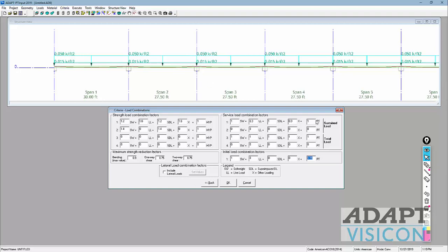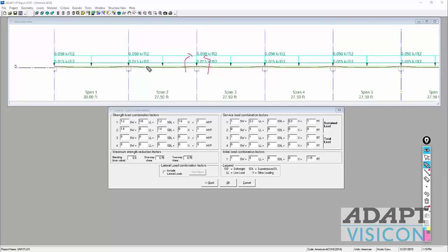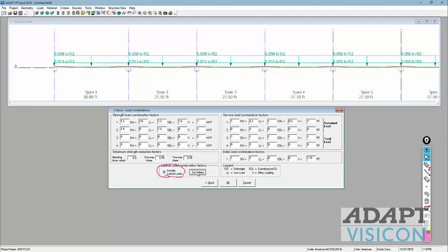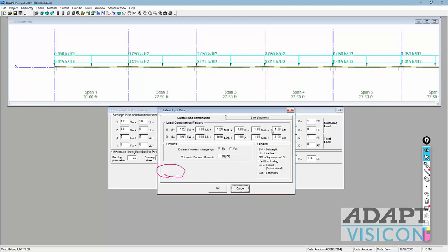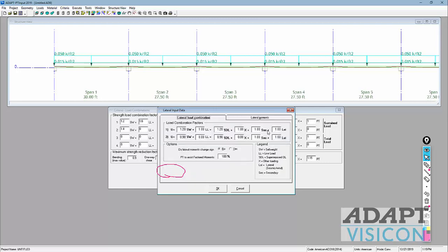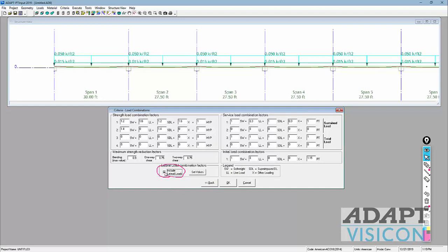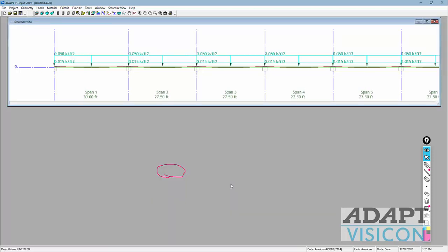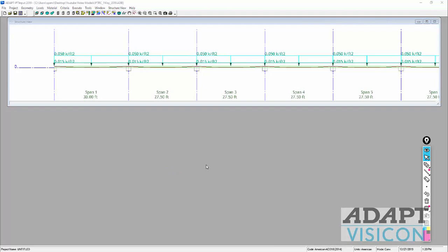You can also, if you needed to, include joint moments at the joints, if this was a frame, for example, a moment frame, and you were designing it also for lateral moments. This really applies more to beams, I think, but we could include lateral joint moments here and also additional combinations, including those lateral moments. So the moments are input in this table. The combinations are then dictated here. Okay, we're going to leave lateral off for this example. I'll go ahead and select OK, and I'm going to save the model. Okay, now that the model is saved, we're going to execute the model.